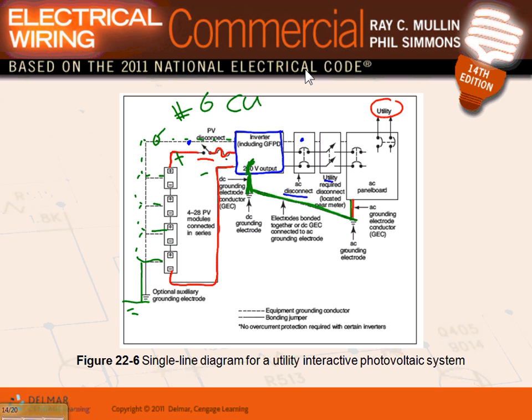Can I get you guys to understand the following? See where the disconnects are located for all these systems on each side of the inverter, 1 for the utility, 2, and the grounding electrode system for the utility as well as the system for the inverter. You have to ground your negative here. The negative will be grounded right at the inverter. Bond the negative to the ground at the inverter. And then you have to have a bonding conductor that goes all the way to the panels and down to Mother Earth. Any question, guys, about that?